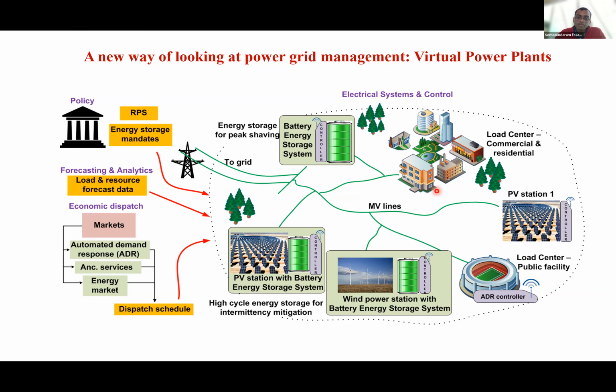So this same hospital has another line going back to the main feeder, but that is kept normally disconnected. During abnormal operating conditions, they connect that normally disconnected line so that the critical loads continue to receive power. So these things are taken into account already.